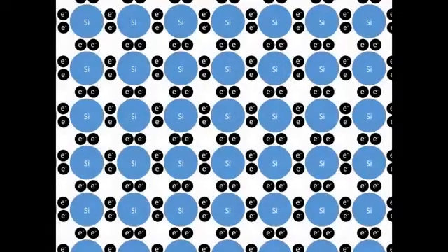We see here a 2D representation of a pure silicon crystal where all the valence electrons form rigid covalent bonds, are immobile, and don't allow the flow of electricity. This material structure is identical to our intrinsic sample when in the dark, which has a very low conductivity.